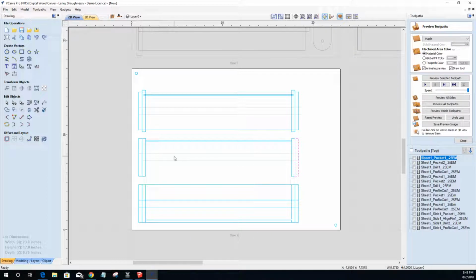We're here. Go into node editing, delete that span. Same thing on this side, delete the inside span. Okay. While we're here, might as well select that one and join with a straight line once, twice. Okay, done. Now we can take our rabbits or dados, vectors, and we can go ahead and